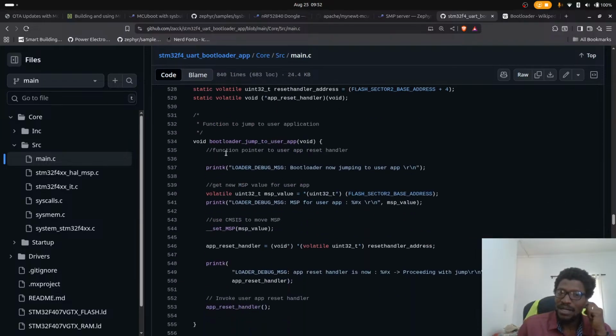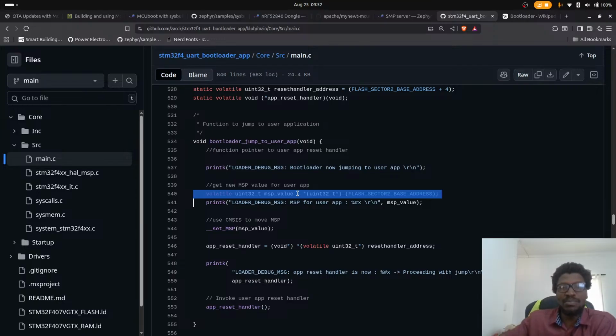app. When you're jumping to user app, you're just jumping to the entry point's memory location. The entry point of your user application, you jump to that. An entry point is a function, the function that starts, basically main. You put main somewhere, and then another program will start up the device and then point the execution registers to where your main is. That's what a bootloader is, regardless.